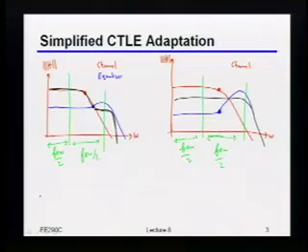If I'm not equalized properly, in this region here I'm totally flat at this level, but then up in the upper half of the band, I have this kind of roll-off. So as long as the signal that I'm transmitting is relatively white, does that make more sense now? Whereas notice here, it's flat in this band. It's also flat in that band. For some reason I thought the second half was going past the bandwidth. Oh no, it shouldn't be.